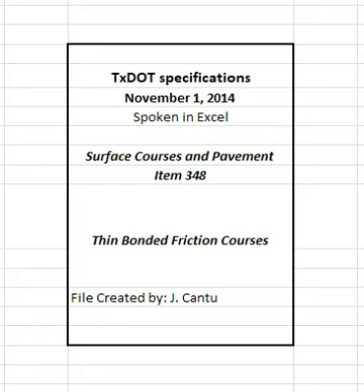3.1.1.1 Tractor unit. Supply a tractor unit that can push or propel vehicles, dumping directly into the finishing machine to obtain the desired lines and grades to eliminate any hand finishing. Equip the unit with a hitch sufficient to maintain contact between the hauling equipment's rear wheels and the finishing machine's pusher rollers while mixture is unloaded.